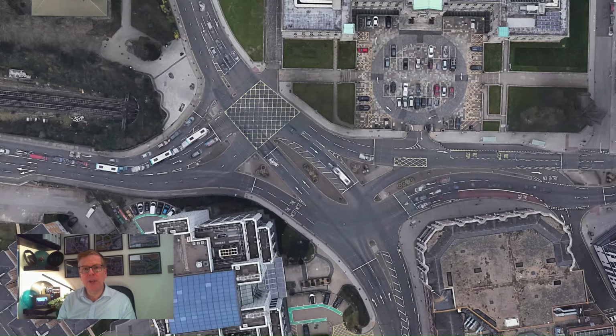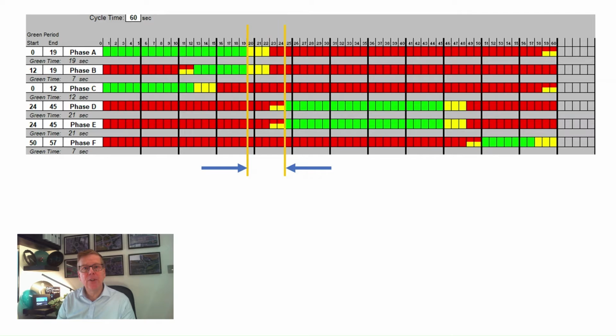Although the values of each intergreen timing can be altered within the TSC, there is a minimum limit value that stops these being changed accidentally or maliciously to an unsuitably short period of time. As with the conflict matrix, this is an important safety period, therefore cannot be circumvented in operation. The intergreen, therefore, ensures that the flow of traffic from the terminating phase has passed before the subsequent phase starts to move.